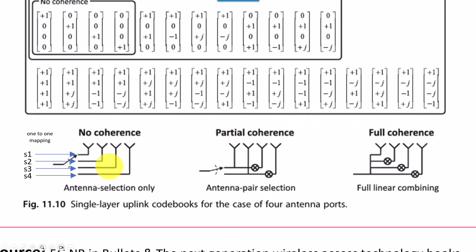So why? Because if I'm assuming this example, you have 4 different streams. So in terms of full coherence, what will happen? Stream 1 will be transmitted 4 times using the 4 ports, for example, at phase 0, phase 90, phase 180, phase 270. Then the same for stream 2, again transmitted 4 times through the different ports, and again stream 3 and stream 4 and so on.